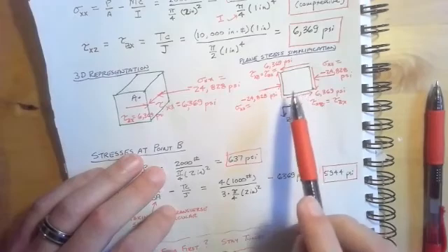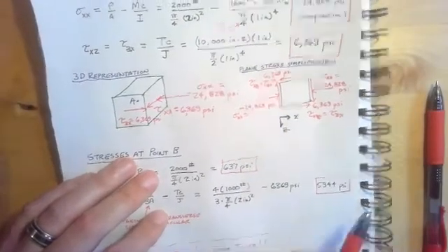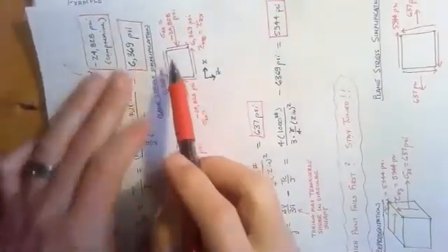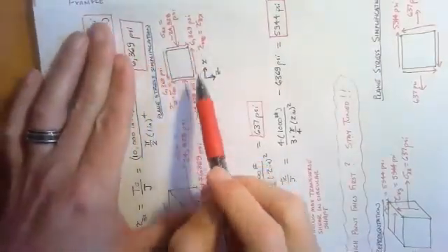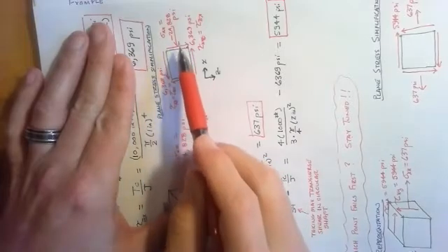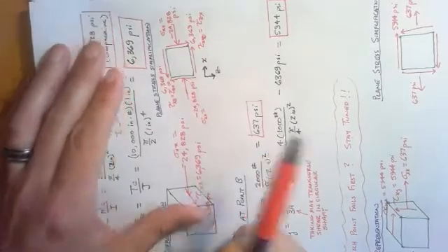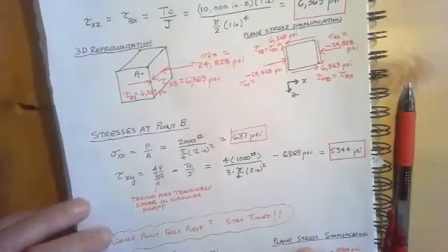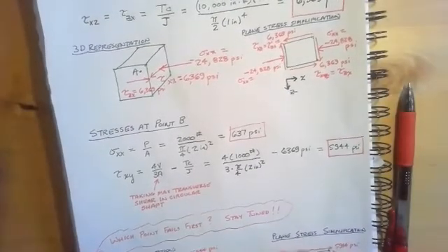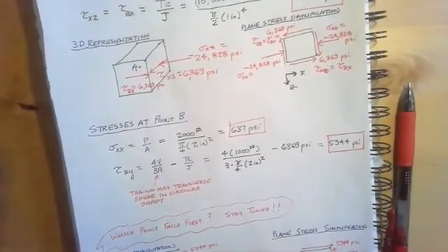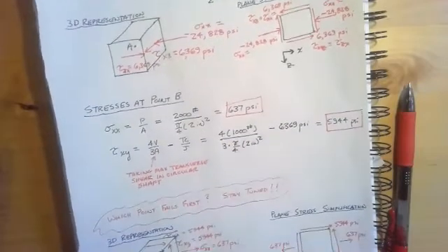So all of these stresses are in the plane, and if I take a look at this and I rotate my paper to the side like this, you'll see the positive convention here for the shear stress, and this would be a negative number for compression. So that should explain to you how we would get a plane stress simplification, and we'll see later on in the lessons that plane stress simplification allows us to investigate a lot of important things for practical problems.